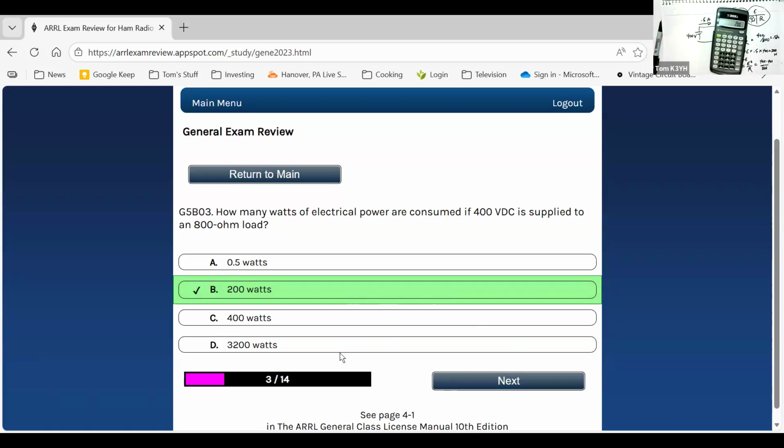Okay, so this was DC power. Calculating AC power is the same, but you have to make sure that you factor the voltage appropriately, because remember, we have an equivalence: the AC voltage that is equivalent to a DC voltage that would generate the same amount of power is called the RMS voltage. So we have to calculate that, and I'll show you how we do it.